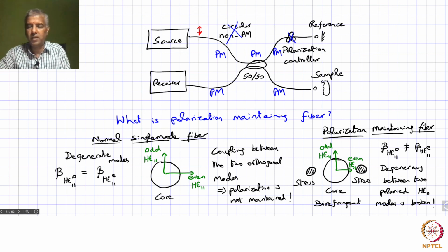The distribution of strain or temperature along the length of the fiber is random in nature, and that means that the phase that evolves is actually random in nature. It actually ends up changing with respect to time. Okay, and so that is changing, and the refractive index here is also changing randomly, and because of that you have a random phase noise component.